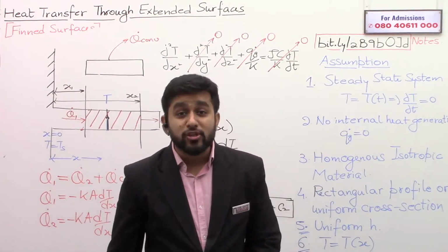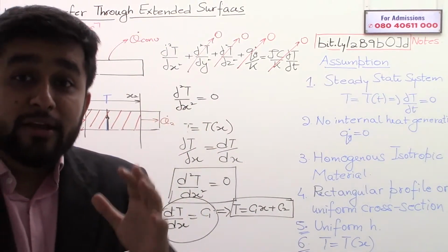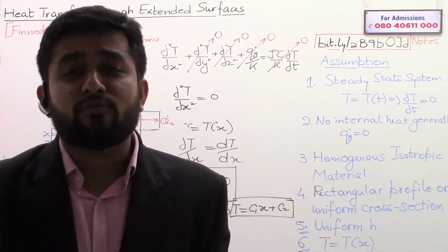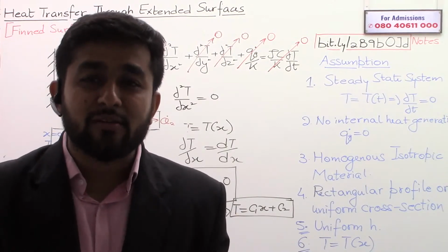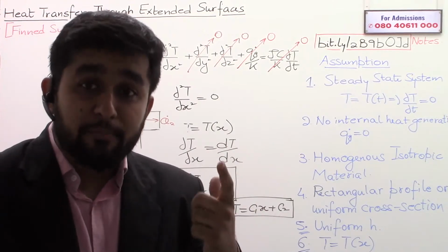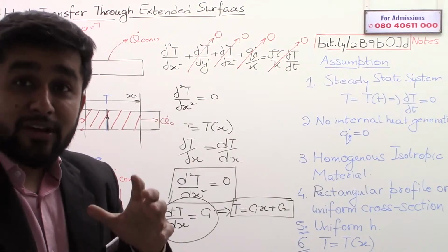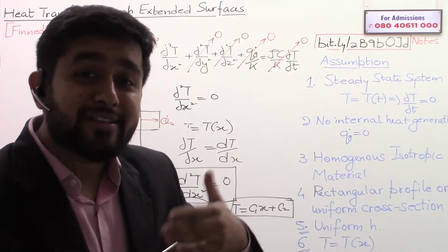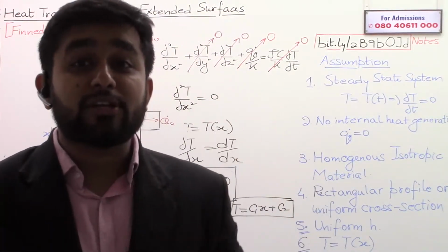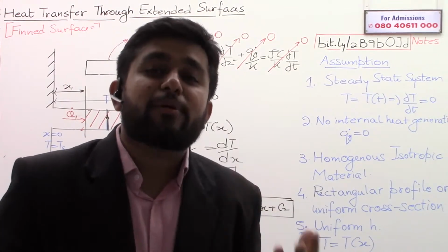And what is that wrong assumption? The temperature is only a function of x. But actually inside the material, temperature is a function of x, y, as well as z. So actually our assumption was wrong. And why did I take this assumption? Because I cannot solve the three-dimensional problem. So if you are taking a simple assumption and you are not getting results from the heat conduction equation, then definitely you should use some other method. So particularly in fins and also in lumped parameter analysis, we do not use the heat conduction equation. We use another method of solving it.